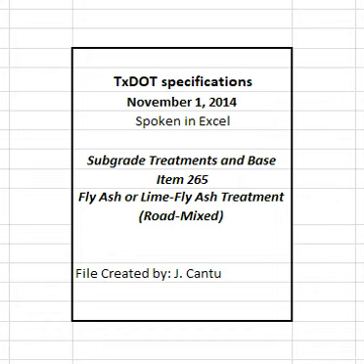4.5 Reworking a Section. Reworking includes loosening, adding material or removing unacceptable material if necessary, mixing as directed, compacting, and finishing. The Contractor has the option of removing failing material and replacing it with acceptable material. Add LFA when reworking LFA-treated sections, or FA when reworking FA-treated sections, at the rate of at least 25% of the percentage determined in Section 265.2.7, Mix Design, as directed.